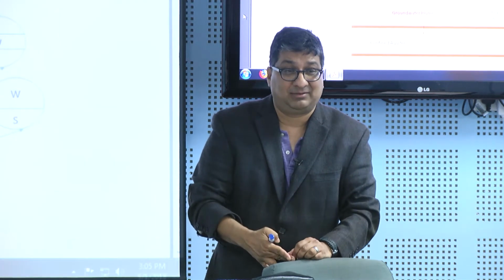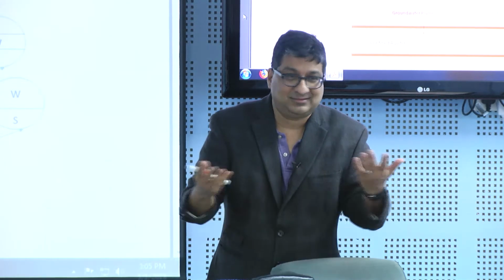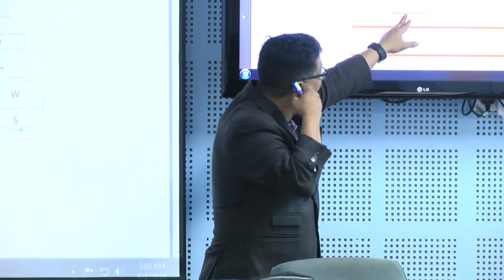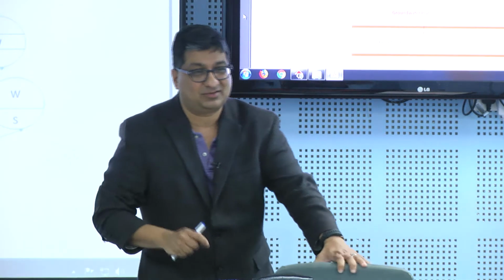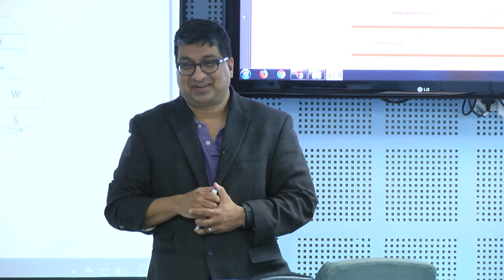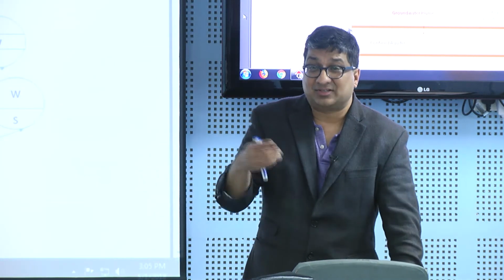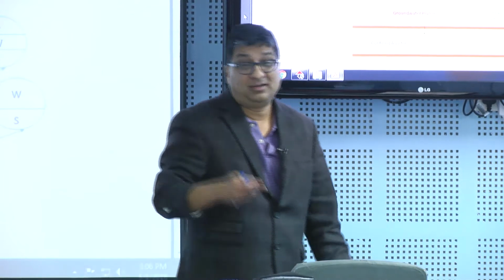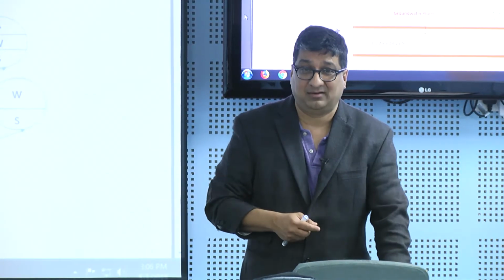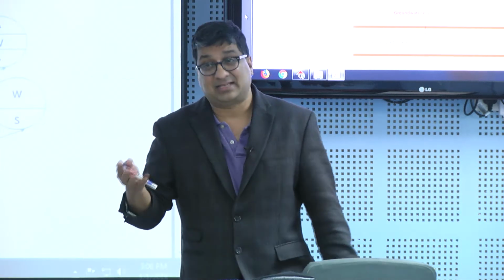Everybody knows the Streeter-Phelps equation. BOD, DO sag, same concept. So what about here in the unconfined aquifer? What do you think would be the dissolved oxygen concentration? Greater than 8, less than 8. Let's say in the vadose zone it's about 8. Would you expect it to be more or less? Less. Typically in an unconfined aquifer, your numbers are somewhere in the 3 to 4 range. Of course, we don't have any fish in there because the pores are all filled with sand. But that's typically where we are.